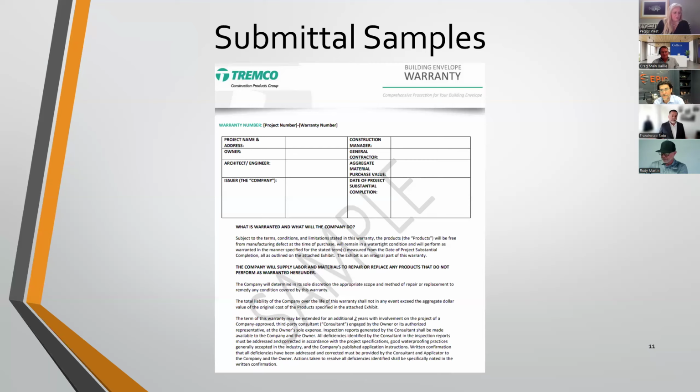And the biggest pushback that we get from manufacturers is, well, did you have a track to walk on? When your guy was going up there to do service on the AC equipment, did they let a piece of metal or a screwdriver or something fall down and puncture the membrane? But short of that, if you have an otherwise properly installed roof, but you still have water going under there, that's where warranty claims I've seen have been successful. Other than that, most of the time it doesn't even come into play because something else is going on.